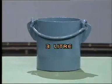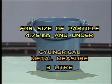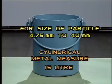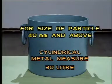We also need a cylindrical metal measure of 3 liter, 15 liters or 30 liters capacity according to the size of the coarsest particles of aggregate. For size of particle 4.75 mm and under, a cylindrical metal measure of capacity 3 liters is used. For size of particle 4.75 mm to 40 mm, the measure of capacity 15 liters is used. For size of particle 40 mm and above, the measure of capacity 30 liters is used.